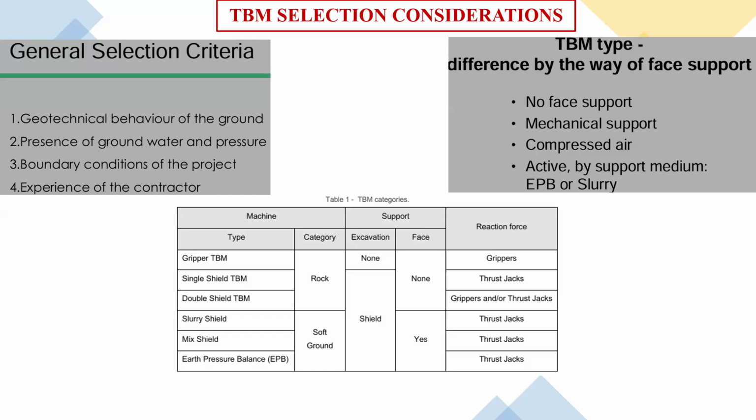But when you are launching the TBM, definitely you don't have anything, so there will be no face pressure inside. That is why I told you that until 80 or 100 segments are installed. If you take 80 segments of 1.4 meter length, it will be 112 or 115 meters. Once that much has gone, then it can get the desired face pressure, as well as you can work in full closed mode.